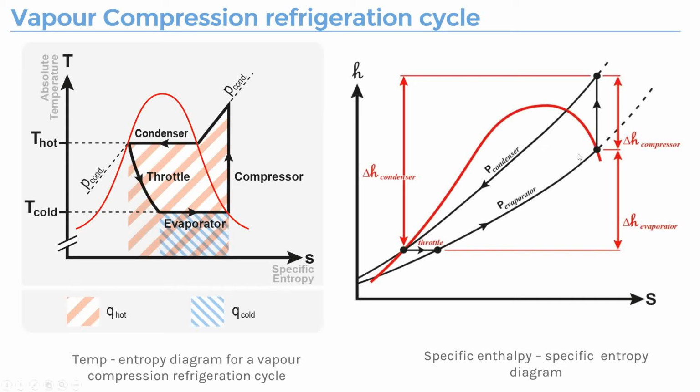So there are lots of charts and tables you can utilize to solve all those problems. The pH diagram is one kind where you find all the values of H, the enthalpy values. And another chart you usually use would be a TS diagram, which is temperature and entropy.